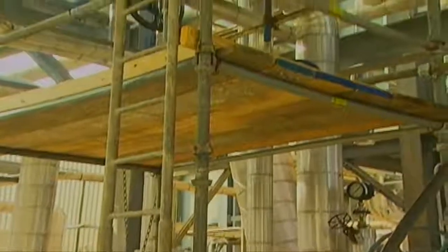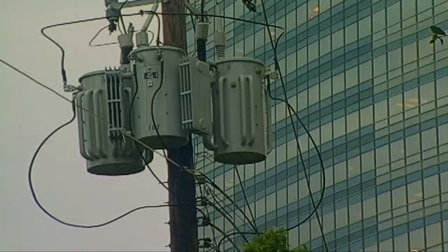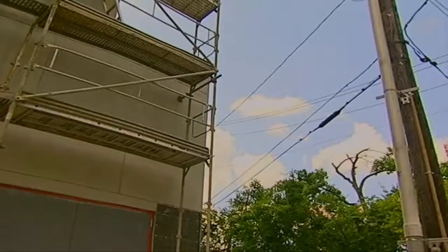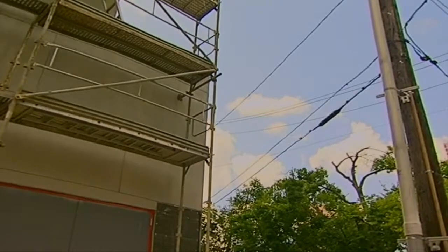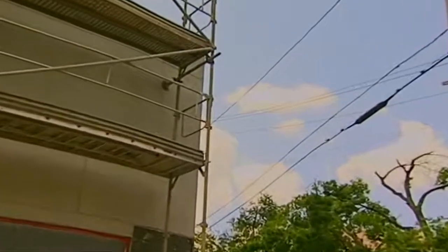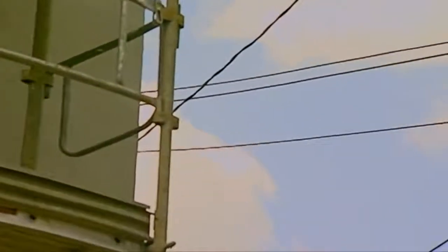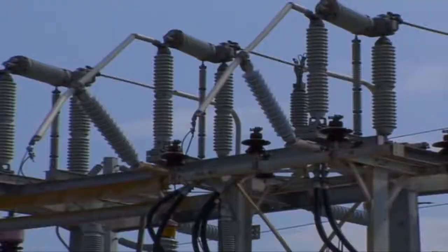Scaffolds are usually made of metal and are built upward to reach elevated work areas. Electrical lines are often present overhead. The combination of both can be very dangerous and can put workers at risk of electrocution. Proper clearance and following basic rules can help eliminate the risk. Scaffolds should be constructed so that there is at least 10 feet between it and any power line. This 10-foot distance applies to any part of the scaffold and tools, equipment, or material that might be used on the scaffold. As a general precaution, the 10-foot rule should always be applied.